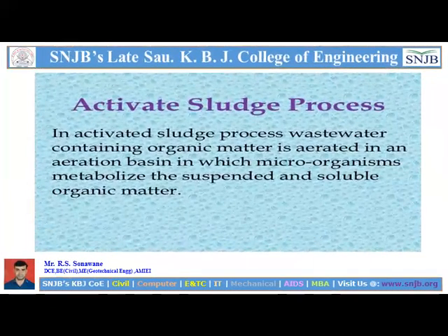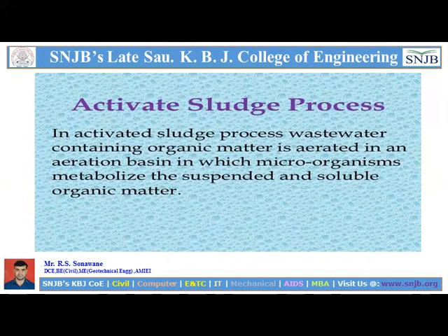Then activated sludge process. In the activated sludge process, wastewater containing organic matter is aerated in an aeration basin in which microorganisms metabolize suspended and soluble organic matter.